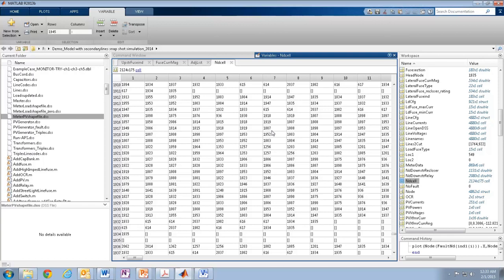So this node cell matrix can be very useful for several purposes. For protection coordination, for a given fault we can trace all the upstream protection devices, fuses, reclosers, till we reach the substation relay, and so this can be used to determine the coordination for different types of faults. Similarly, for model reduction, say if your objective is to combine all single phase loads, club them together and connect the combined load at the nearest three phase section, once again this node cell can be useful for that.